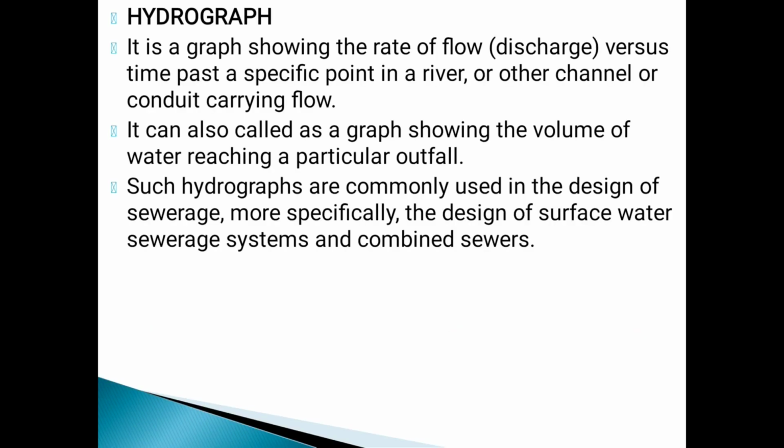At first, what is meant by hydrograph? It is a graph showing the rate of flow, discharge versus time, past a specific point in a river or other channel or conduit carrying flow. It is also called a graph showing the volume of water reaching a particular outfall. Such hydrographs are commonly used in the design of sewers, more specifically the design of surface water sewage systems and combined sewers.